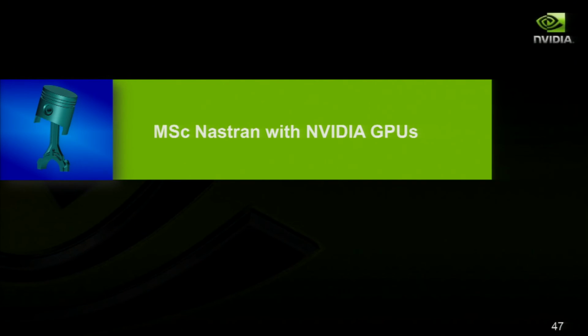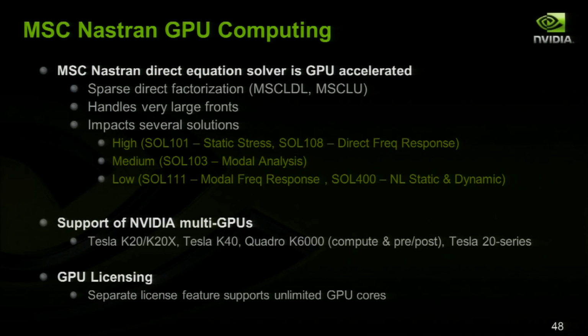So I'm going to briefly touch upon MSC Nastran, another application in structural mechanics that we accelerate, and we've been successful. In MSC Nastran, the direct equation solver is GPU accelerated. The factorization is sent to GPUs, and it can handle very large fronts. It also impacts several solutions such as static stress analysis, modal analysis, and modal frequency response studies.